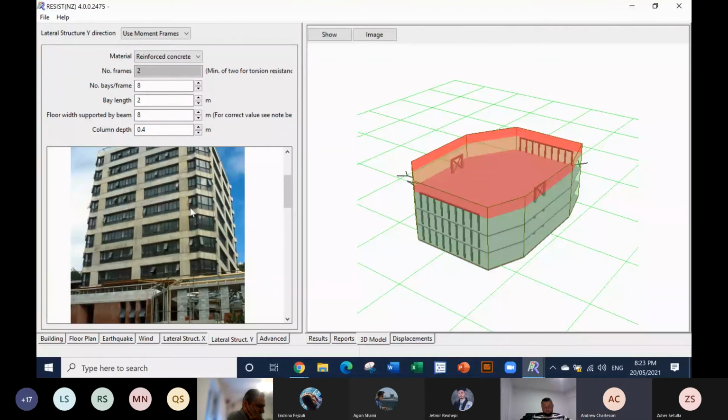A moment frame is able to be integrated into the building function, usually a lot easier than a braced frame. And it's because architects like the ability of a moment frame to be integrated in with their planning and their aesthetics. This is what drives the use of moment frames. It's purely driven by architects. The engineers would prefer that architects use structural walls to resist earthquakes, because structural walls have a far better track record of survival in earthquakes.